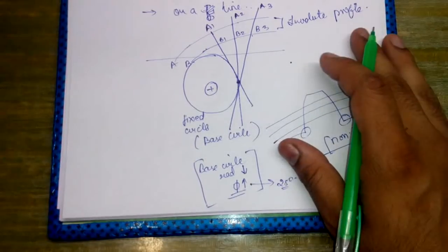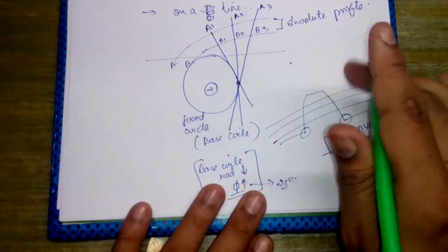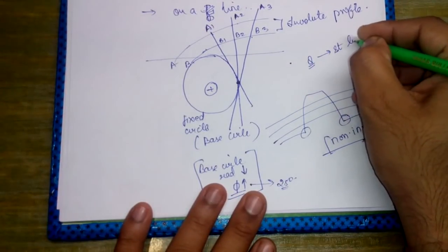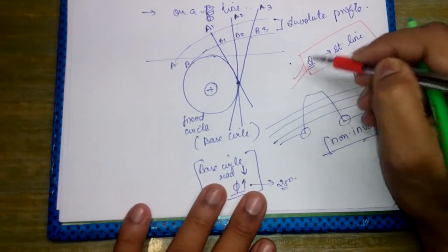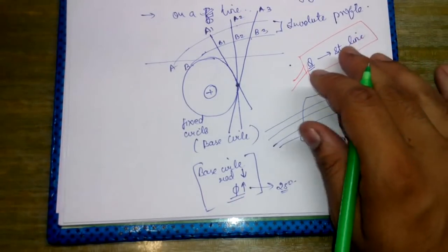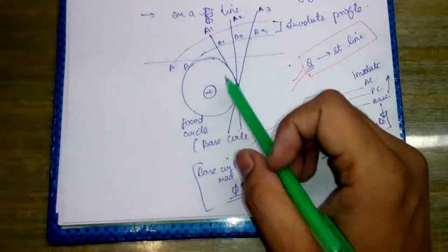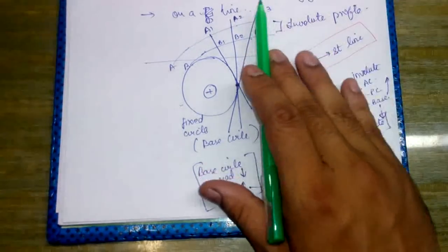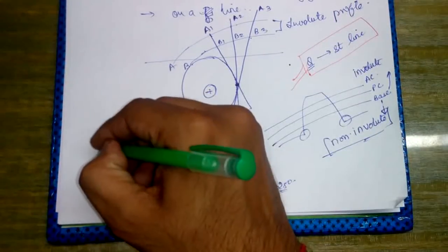और यहां पर हमने ये देखा कि जो पॉइंट ऑफ कॉन्टैक्ट है इट इज एक्चुअली ट्रेवलिंग अलोंग द लाइन ऑफ एक्शन। तो लोकस ऑफ क्यू पॉइंट जो था वहां पे, द लोकस ऑफ क्यू पॉइंट वुड बी अ स्ट्रेट लाइन। ये भी बहुत इंपॉर्टेंट क्वेश्चन है जो हमसे बहुत सारे एग्जामिनेशंस में पूछा गया है कि व्हाट वुड बी द लोकस ऑफ द पॉइंट क्यू। ठीक है, तो द टाइम इंटरवल इन विच द क्यू इज ट्रैवलिंग फ्रॉम द स्टार्ट पॉइंट टू द एंड पॉइंट ऑफ द एंगेजमेंट, उस टाइम को हम कहेंगे कॉन्टैक्ट पीरियड।